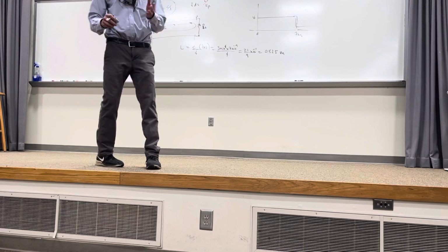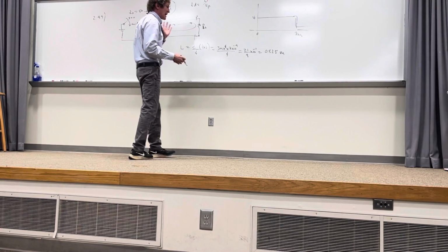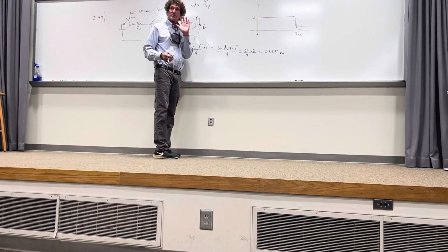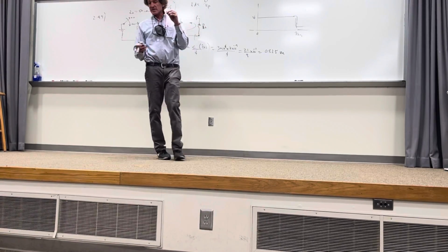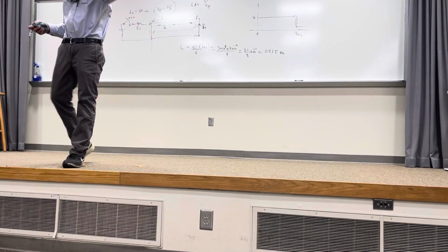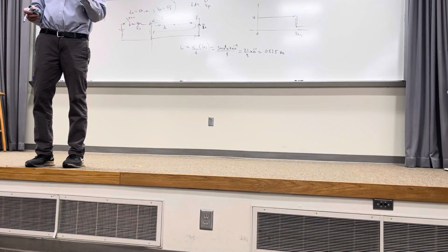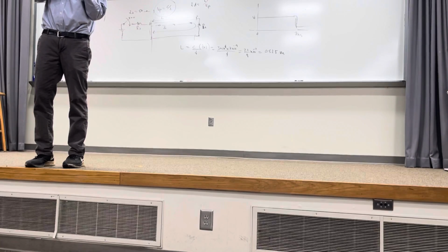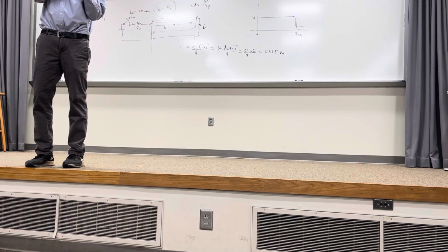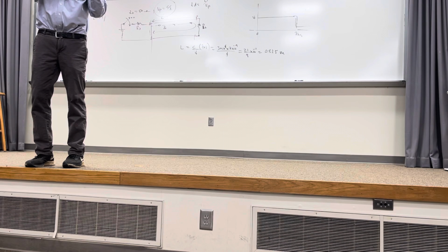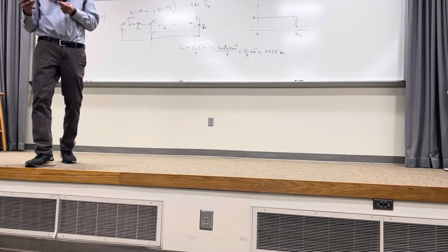Just realize this. Whenever they're talking about these problems, it's time domain reflectometry. This is the way you find the length of a cable through a wall. If it's a matched load, like a coax line, just put a short there. Then you initiate a pulse and record the data on a standard network analyzer, where you let the pulse go, hit, and reflect back, and you see the time delay. That time delay gives you all the information about the length of the line, as long as you can assume something about the velocity of the line.